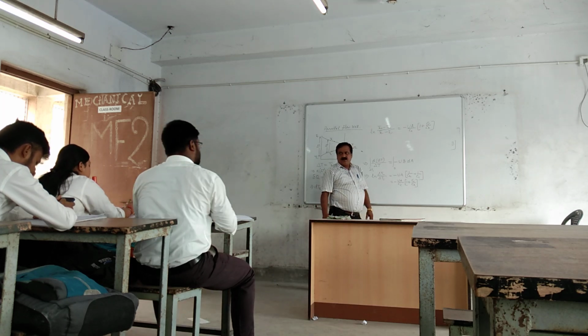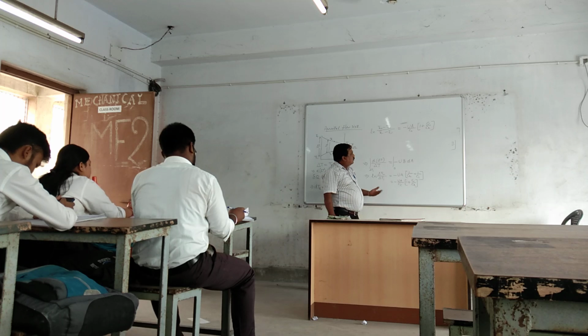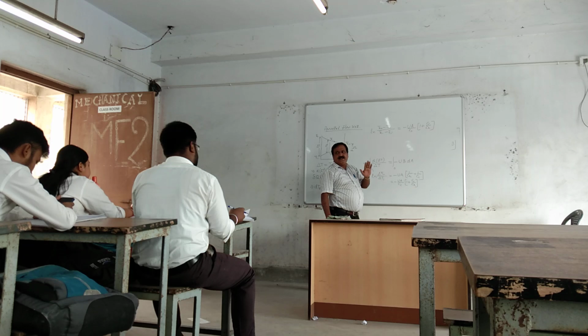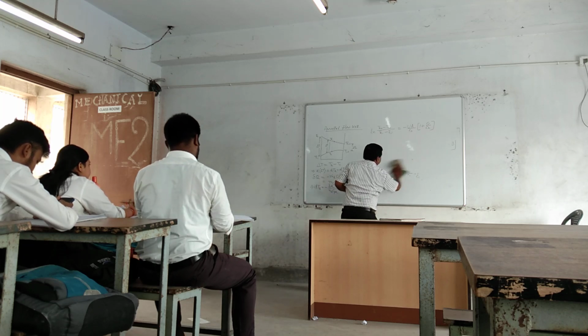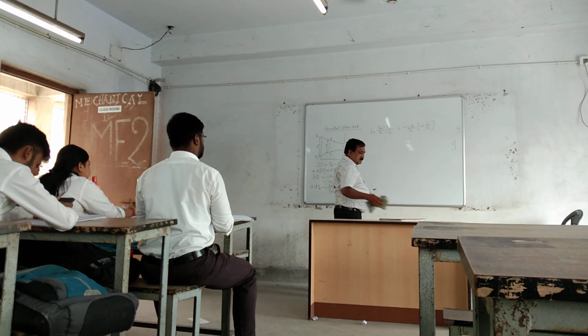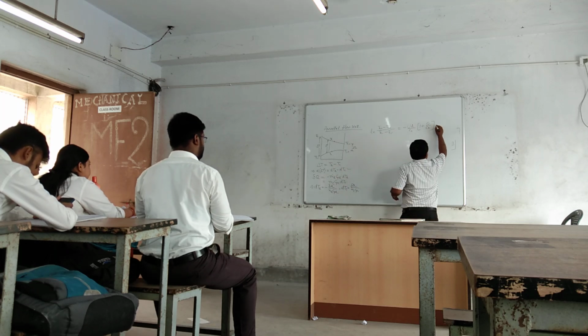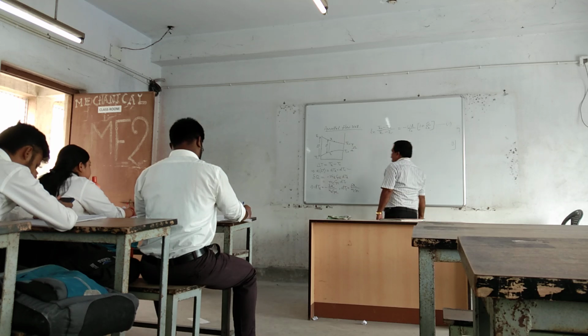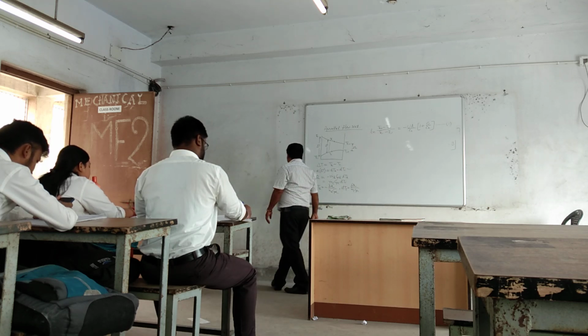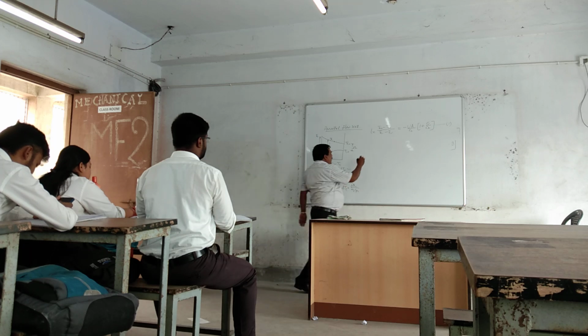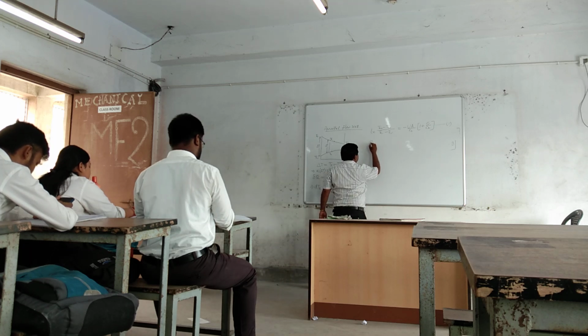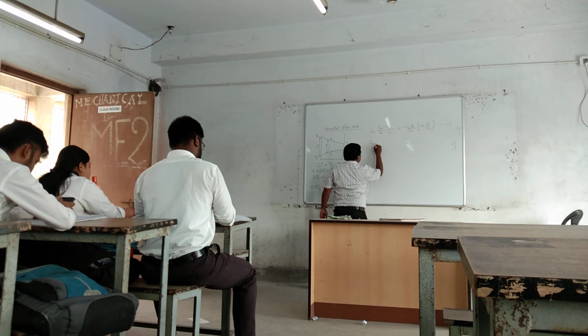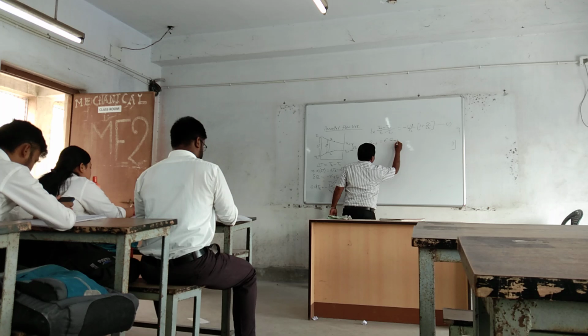Yes. Okay? So what we have to do? We have to transfer all the outlet temperatures into the inlet temperatures. How to do it? See, let us write this as equation number 1. Now what is Q actual? We have defined it for effectiveness. Q actual is equal to epsilon into Q maximum.